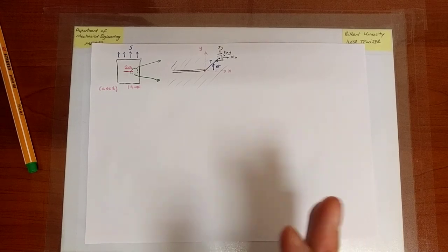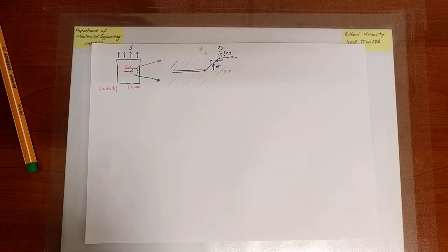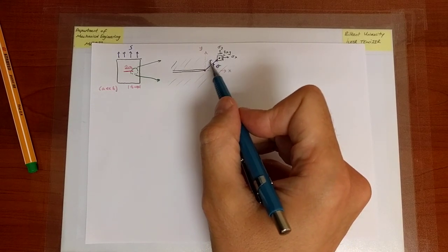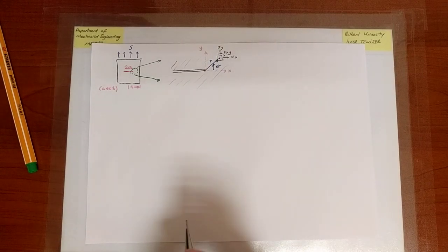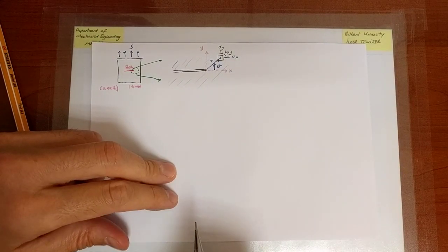In reality, we are assuming a brittle material, so plasticity can be omitted, but brittle materials have an ultimate strength. We are thinking about an ideal world where the ultimate strength is infinite and therefore infinite elastic stresses can be sustained, and I'm trying to calculate the distribution of the stress in the vicinity of the crack tip at an arbitrary point away from the tip of the crack.